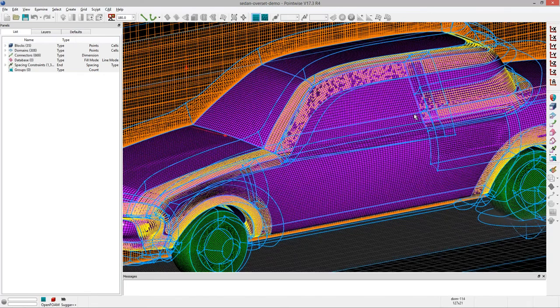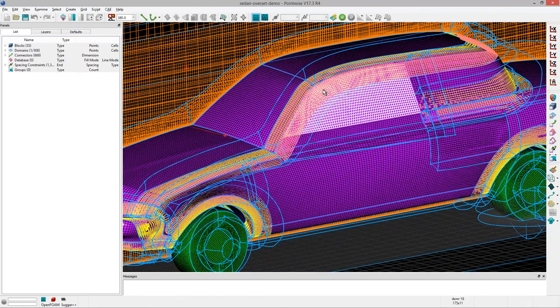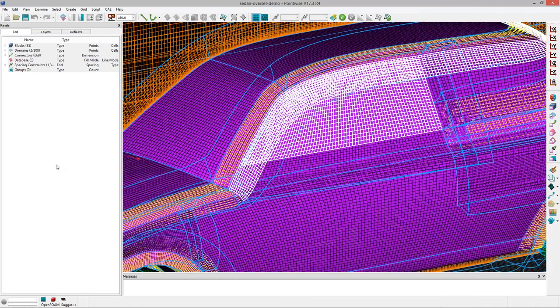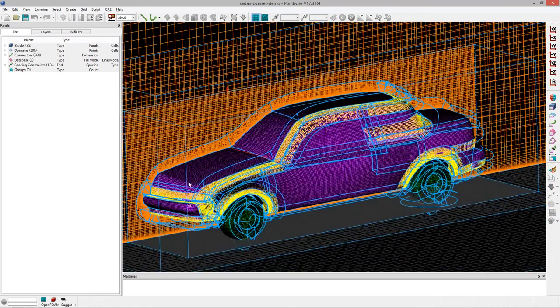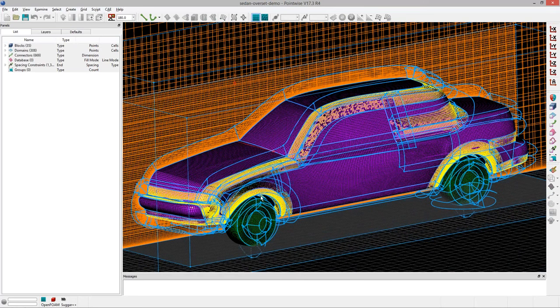You'll notice that, for example, on our surface, all of our surface grids are overlapping. I've just selected 2 structured surface meshes in Pointwise. In Pointwise, you create these just like you create any other domain, which is what we call a surface mesh in Pointwise. You'll notice that they are overlapping by 6 or more cells, and that the cell areas are roughly equivalent in the overlap locations.